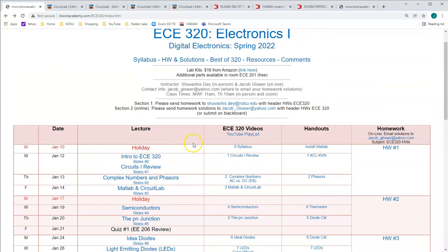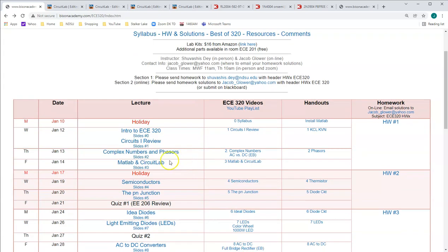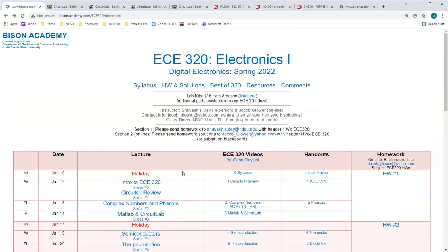And a good way to think about electronics, this is the interface between a microprocessor and the real world. Microprocessors typically have binary inputs and binary outputs. This is how to convert something to 0 to 5 volts to drive the processor, how to convert something that's low power, binary, to something high power, so you can drive an LED, motor, all using electronics.